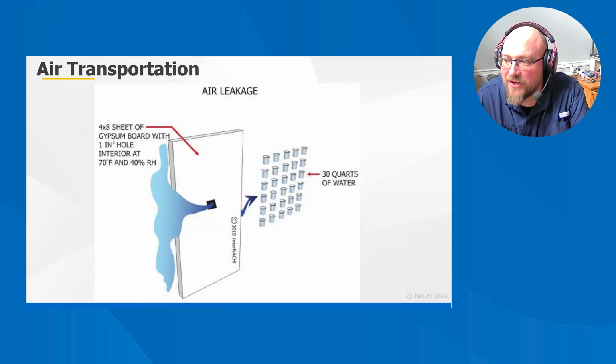The moisture that the air can no longer hold condenses on the first cold surface it encounters, the dew point. If this surface is within the exterior wall cavity, wet insulation and framing will be the result. In addition to air movement, temperature and moisture content can also be controlled.